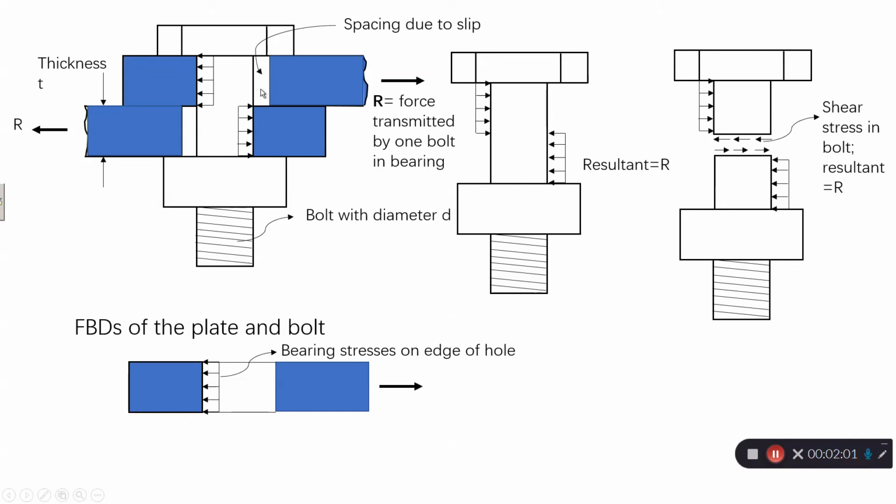On one side and the other side, the bolt is pushing on the connecting plates, and it is this force that causes the excessive elongation of the hole. Also, the failure mode for the bolt itself is shear failure, so it tends to be sheared off along the shearing plane.